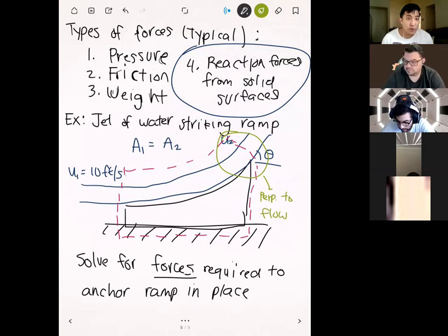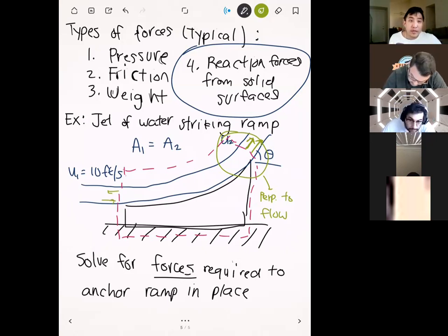And if you remember, we want to do this so that when we compute our dot product u dot n, we just get a whole number and we don't have to worry about any angles. So if we do this here, then the normal vector to that surface will be just like this. And in this particular case, the flow velocity vector will look like that as well. So they're parallel to each other. And then same thing right here. Here the normal vector is pointing that way, and then the flow velocity is pointing in, just like that.